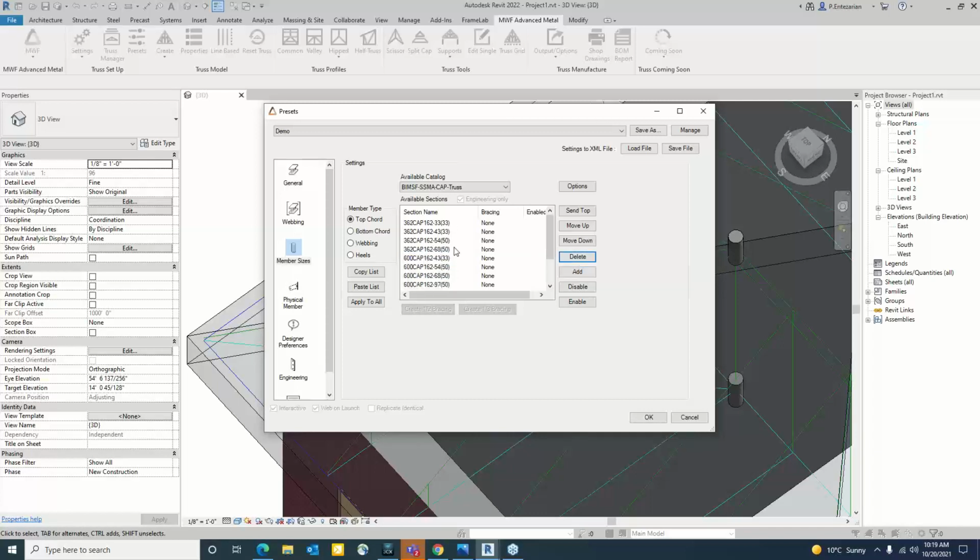What we have here is not all the families that we have in our project. It is actually the pick list that you are creating for the design portion. When you are running the design, each member will get selected and we calculate loads on the member. If it passes, if it's the correct family, it will keep that family. If not, it will move on to the next families on the pick list. So right now for the top chord, the pick list would be these.